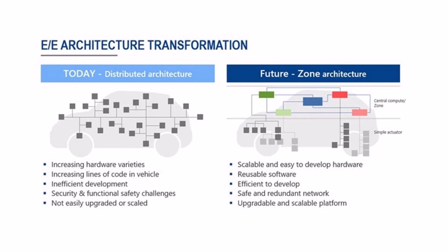The automotive sector is moving from the traditional distributed architecture to zonal architecture. Okay. So what zonal architecture means is you will not have some 70 ECUs. You will have some 4 or 5 zones, and each zone will have very limited nodes, and each node will be connected to the sensors. The sensors could be your vehicle speed sensor, or your temperature sensor, or anything. Okay. So you can just pause your video and have a look at this slide.